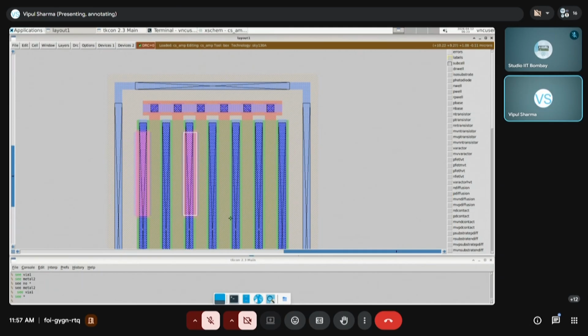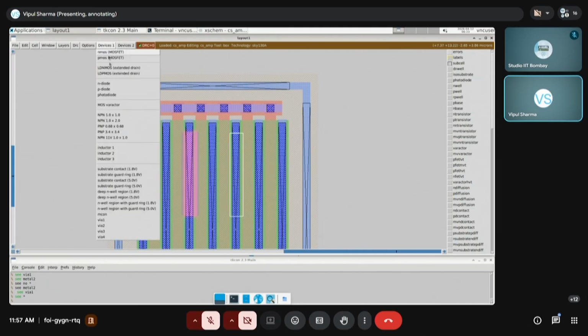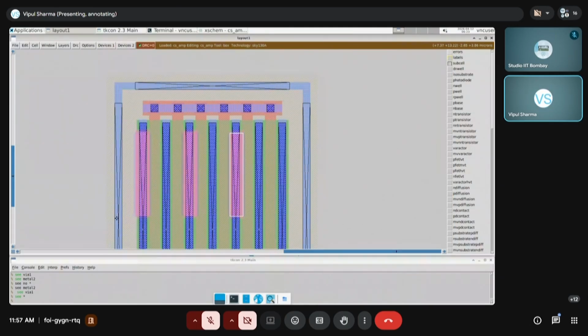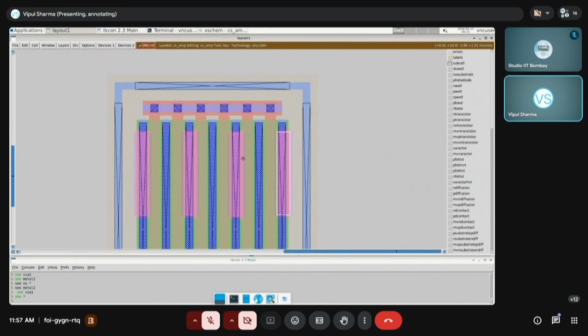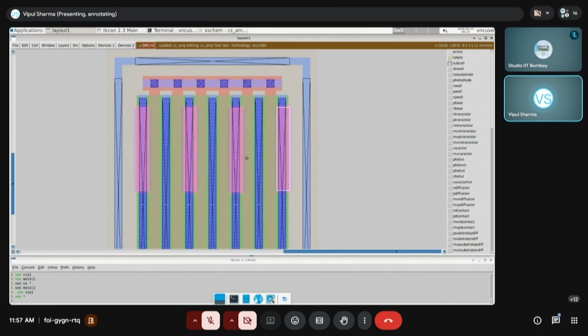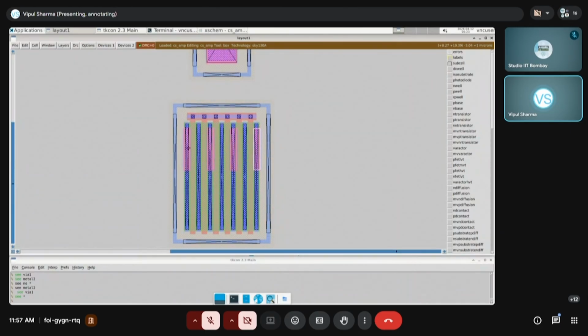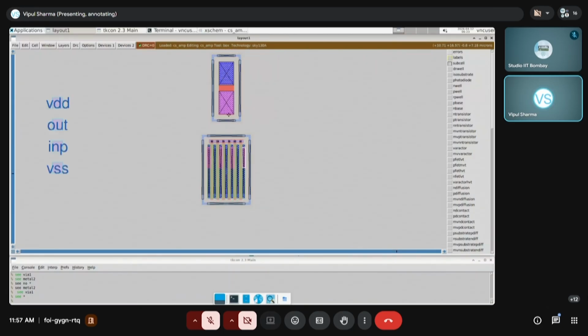via 1, via 1, via 1. Okay. So now all these terminals of NMOS have been electrically connected to metal 2 through local interconnect, metal 1, and the via in between, and metal 2. So now there is metal 2 layer over these both terminals.